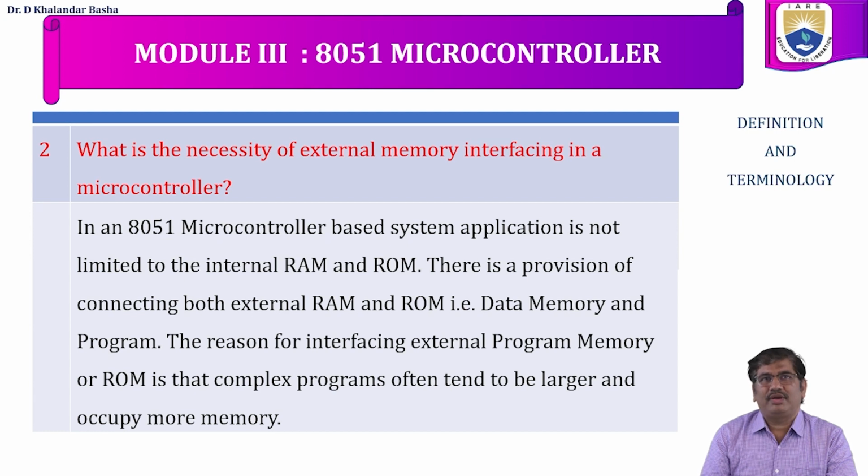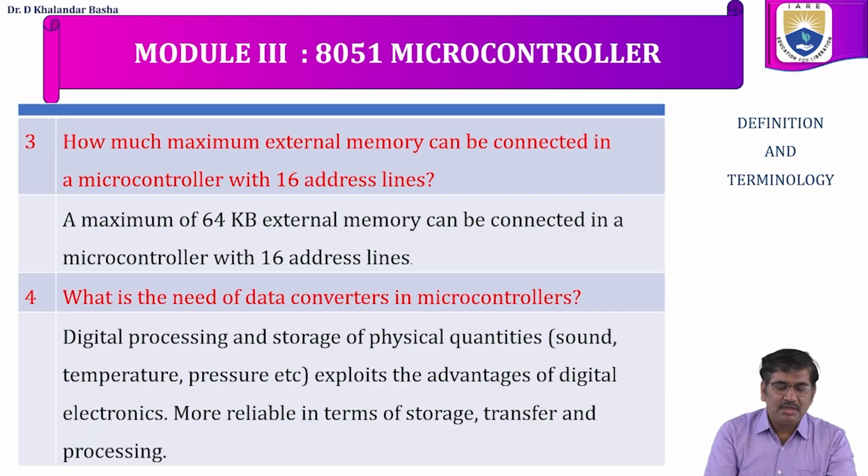So in an 8051 microcontroller based system, the application is not limited to the internal ROM and RAM. There is a provision for connecting both external RAM as well as ROM. RAM is for data memory, ROM is for program memory. The reason for interfacing external ROM or RAM is that complex programs tend to be larger and occupy more space.